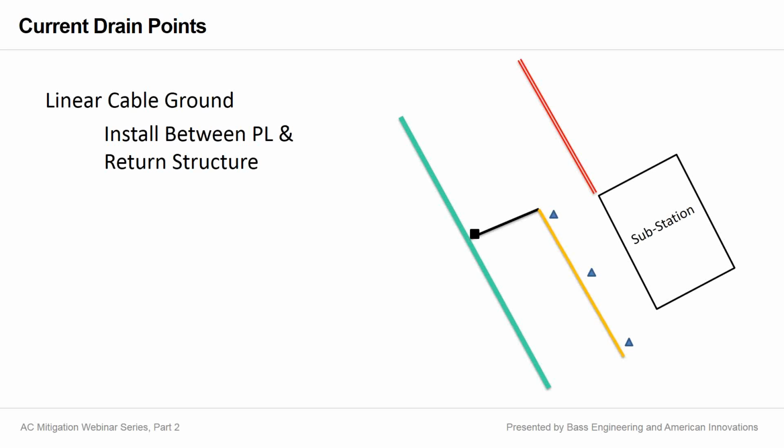One other caveat that you want to think about with the linear cable grounds, many times each one of these systems has its own pros and cons. So you have to consider your right-of-way availability, you have to consider obstacles that may be in your way, but we found the linear cable grounds to be particularly useful in helping us create a shield between electrical substations and